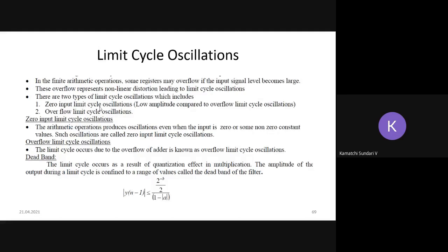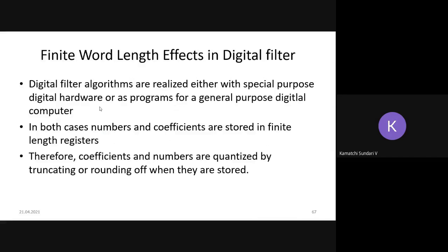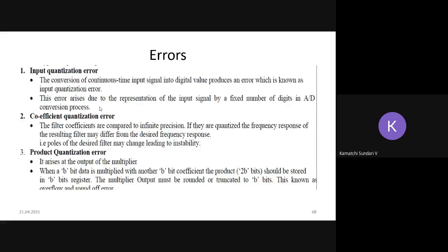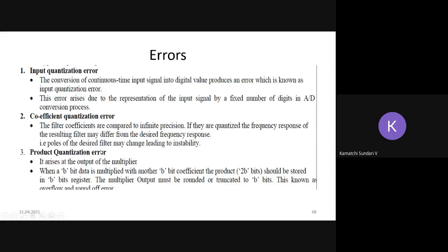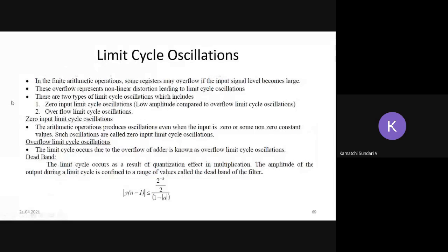Coming to the next important concept, limit cycle oscillation. While looking into the FIR filter, in this case, it is free of limit cycle oscillation when implemented on a finite word length digital system. So, the limit cycle oscillation concept. In finite arithmetic operations, some registers may overflow if the input signal level becomes large.